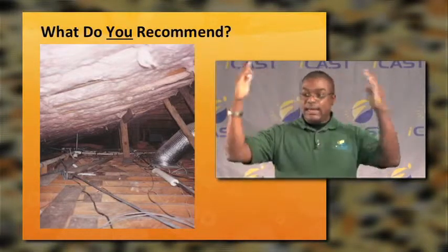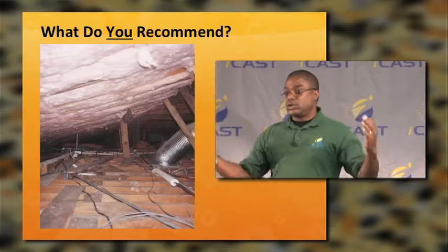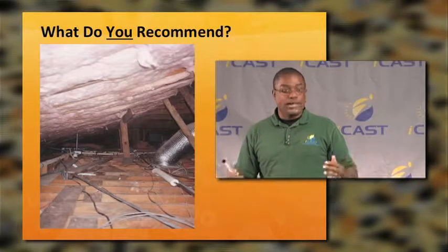So now you have an attic that's filled with conditioned space, but nobody lives up there. So now you heat the space below, and that heat moves its way up into the attic, and it gets stopped at the attic. But there's nobody living up there. You can't use that heat, even though you've kept that heat from going out of the space.